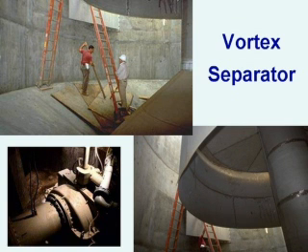What we found in the years of operating this facility is that when it rains, or you know it's going to rain, your rainfall monitoring equipment says, hey, we have a probable event, then the bar screens turn on. They're actually on before the flow comes to them, and they're running at a pretty high rate, so that when the screenings get to it, it's removing them right away. Screenings and grit are flush related. That means they come in quickly, and after the high intensity part of the runoff, you get very dilute waste with very little screening.